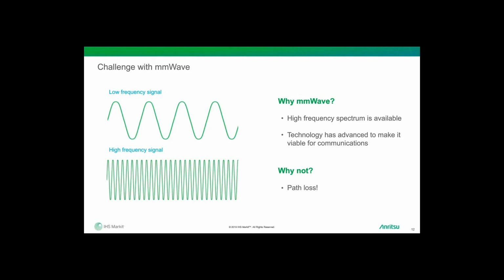We've seen in the first couple years of 5G deployment that most, if not all, countries have really had no problem opening up the millimeter wave bands for 5G. On the other side, though, many countries have struggled squeezing out the contiguous bandwidth that's been required for the 5G speeds. You can really look no further than the U.S. for an example of that struggle. The 3 to 6 gigahertz bands have been tied up in other applications, and due to some of the shared spectrum, there wasn't really a desire from the operators to use those. We've seen similar things across the rest of the world.